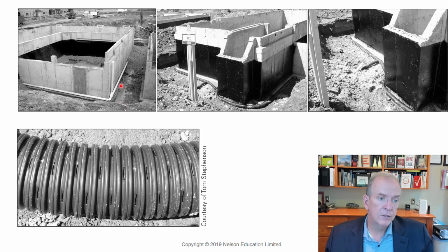In this particular subdivision, it was engineered that stormwater from the roof would go into a separate drain system, which would go into the storm drain, and then eventually that's going to come out through the tributaries, as you saw from the previous lecture, because this is the same houses that we were looking at in this previous lecture, same subdivision. This is your bituminous coating, which is your tar coating that's placed on the outside